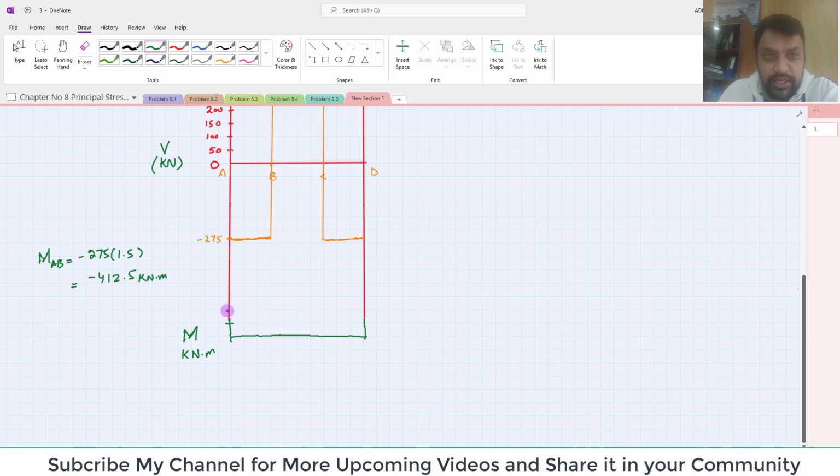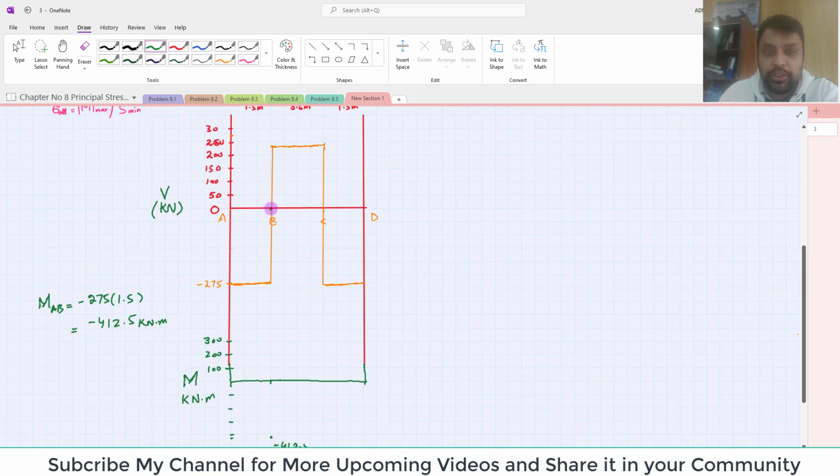Again you have to take an appropriate scale, clear. So let one division be 100, so it will be plus 100, 200 and 300. Similarly here it will be minus 100, 2, 3 and 4. So we have to plot 412.5. So this is 100, 2, 3, 4 and 412 will be somewhere here. Clear? But it will be at point B. So at point B the moment will be this one, minus 412.5. Now again the portion between B and C, the area under this shear force will give you the bending moment.